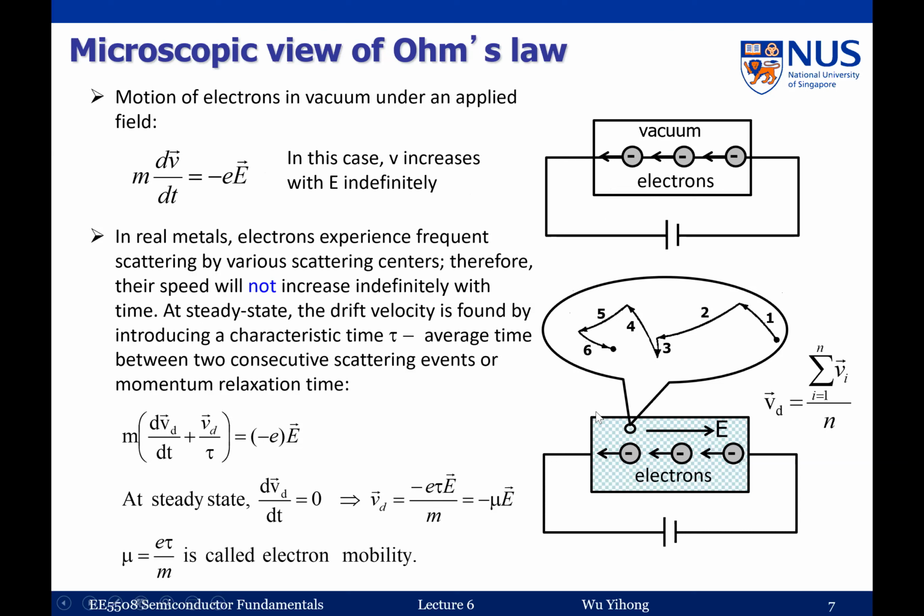However, inside the solid state material, there's another mechanism which is very, very important, and that's called damping. Why is it damping? This means that you have two types of forces. One definitely is a driving force, which is still here, but another force which is proportional to your velocity, but they have an opposite phase. So that basically is the damping force.